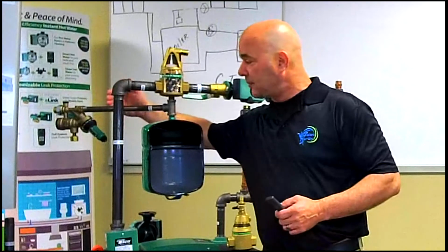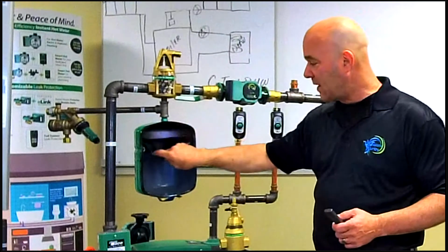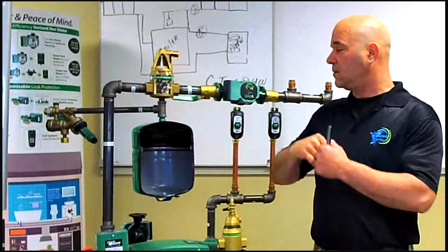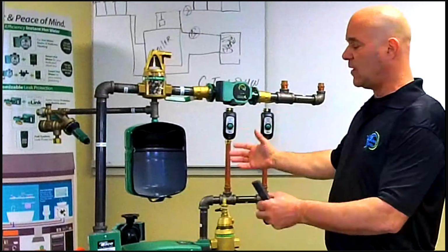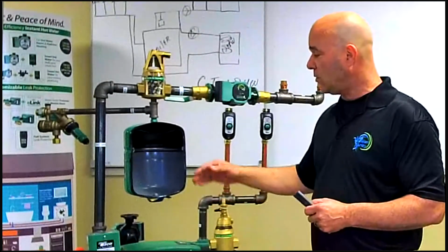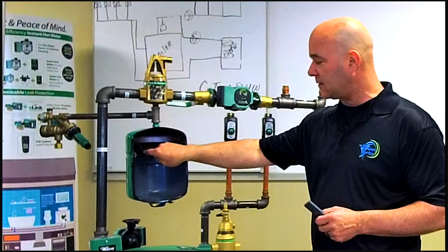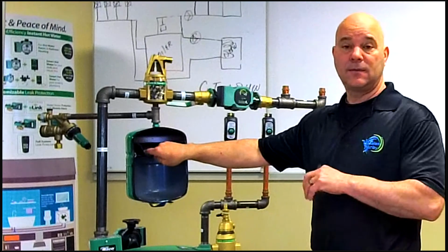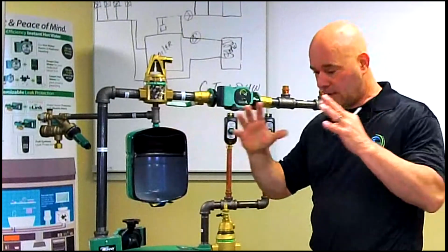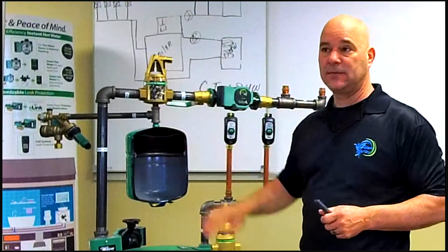Feed valve takes street pressure, reduces it to 12 PSI. So we have 12 PSI on the top of this rubber diaphragm in here, and we have 12 PSI of air on the bottom side. So we fill the system, it's a 12 PSI system, everything is good. We fire up the boiler, we start to heat the water. Our expansion tank is here, we heat the water, it expands, it'll push down on the rubber diaphragm a little bit, and then you'll heat your home. The boiler will start to cool down, the air pressure will push back up because the water has now shrunk again, and this is how the diaphragm works, goes up and down, right?